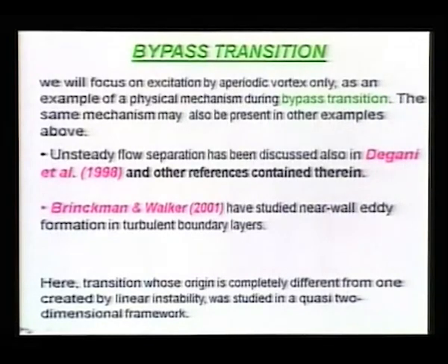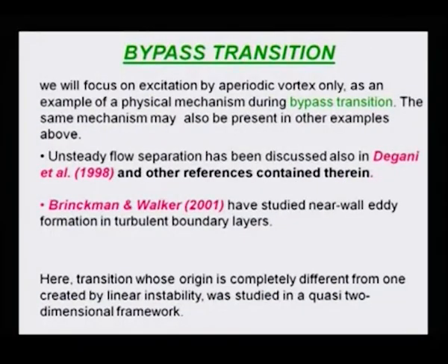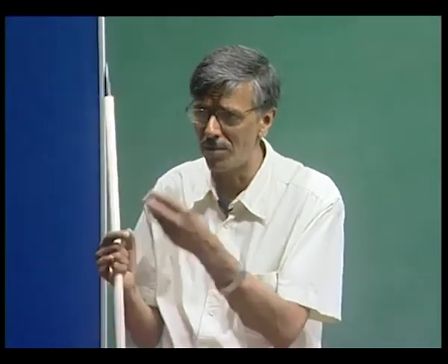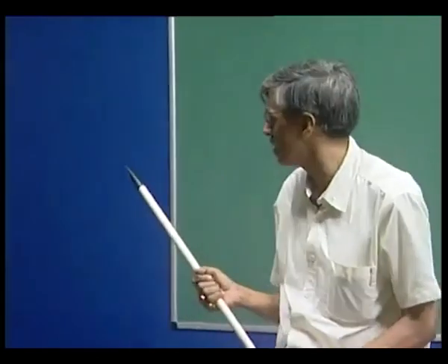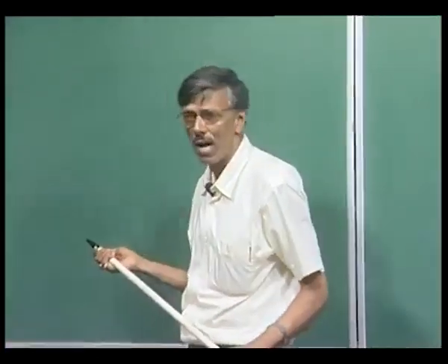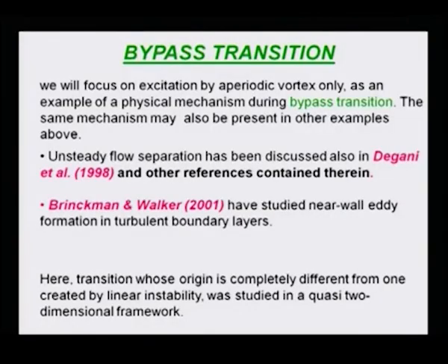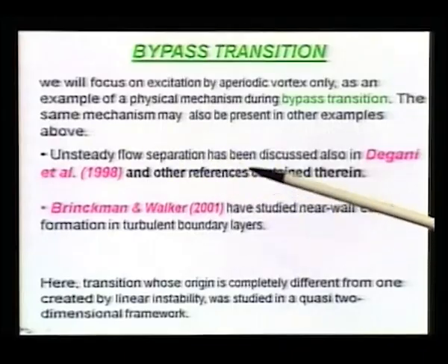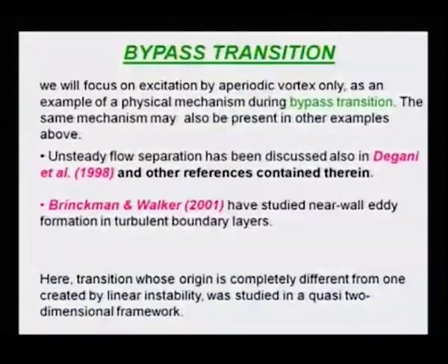And these are the potential application areas where you see such a thing happening. For example, we have talked about unsteady flow separation in fluid mechanics. This is a paper by Degani et al. They wrote about how unsteady flow separation implies separation bubbles which will go along the surface. They also show enhanced skin friction and significant separation. Separation phenomena, we will club them as bypass transition.